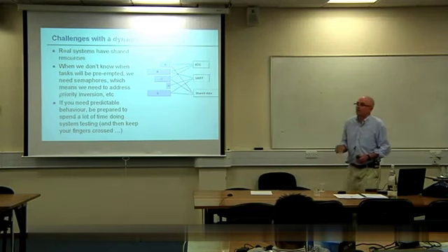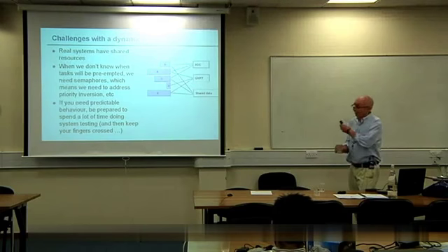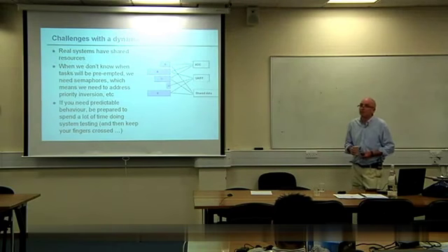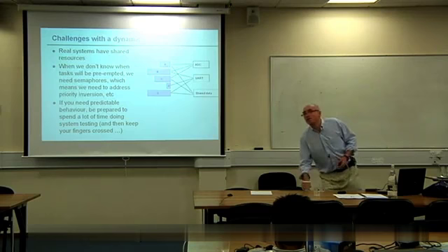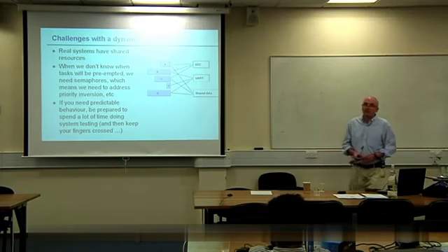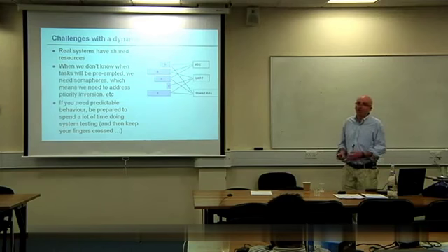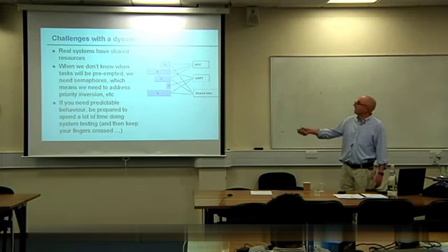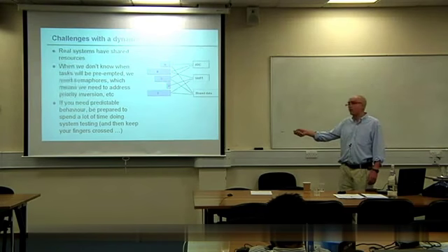It's not cost-free. It's difficult to design these things from the start. And that's the price you pay. To put that together as an event-triggered system is comparatively easy. That's why people like it. And it allows you a false sense of security. You get that system built really quite quickly. The challenge is, I would argue, you will never ever get it tested if it's non-trivial.